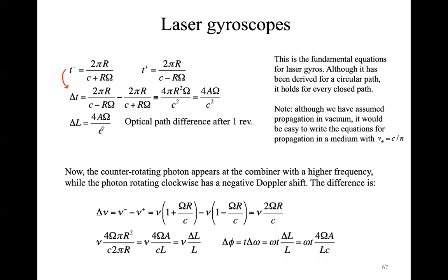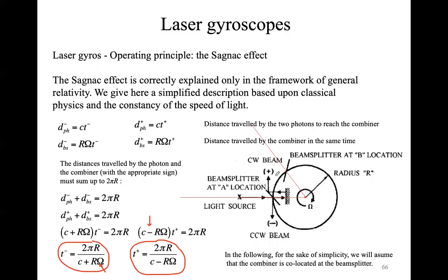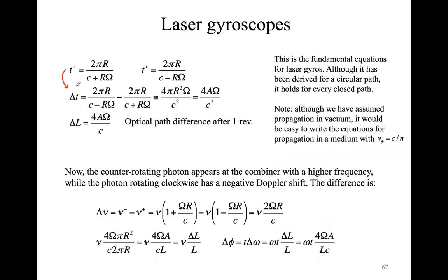And so what you are going to measure is indeed a delta T between the signal moving clockwise and the signal moving anti-clockwise, because they are measured at the detector that is here. If the detector is still, it will be here, so you don't have any signal. Since it is moving because of the omega of the spacecraft, you are able to see a delta T.